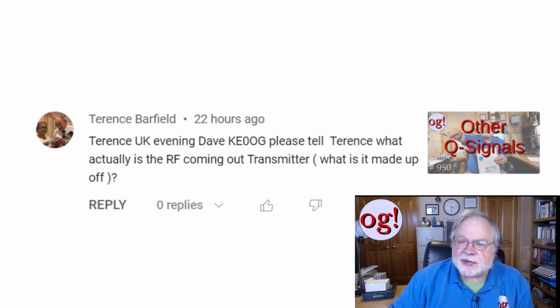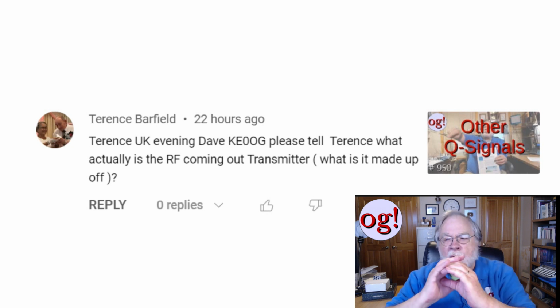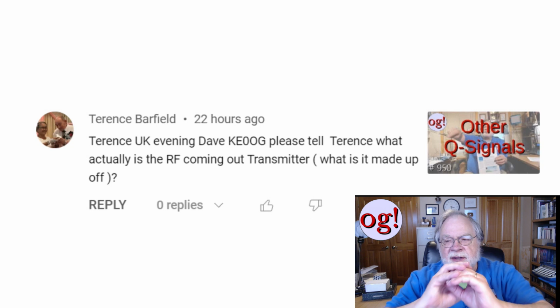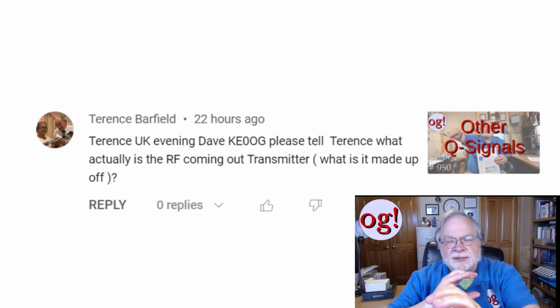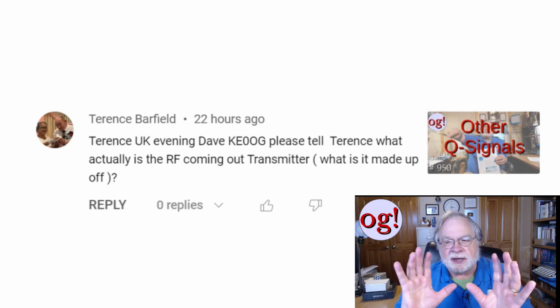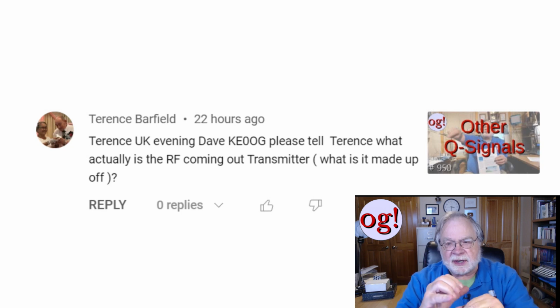And so once it gets into the transmission line, it really is an electromagnetic field. And the electromagnetic field in a coax stays entirely inside the coax as long as you've got 100% shield. Otherwise, it can leak. And that also means other things can leak in.